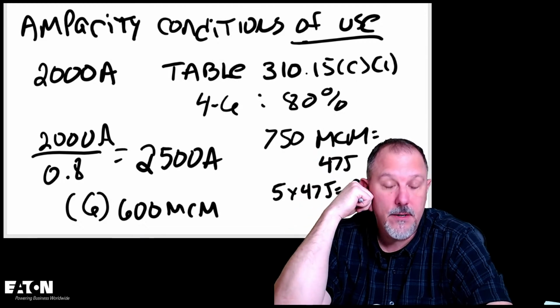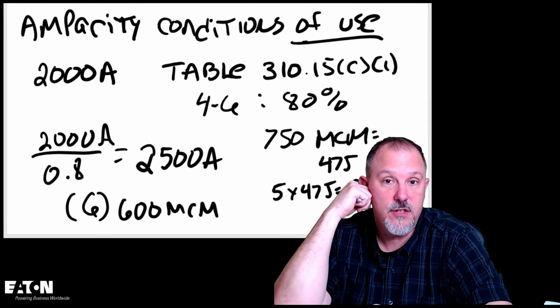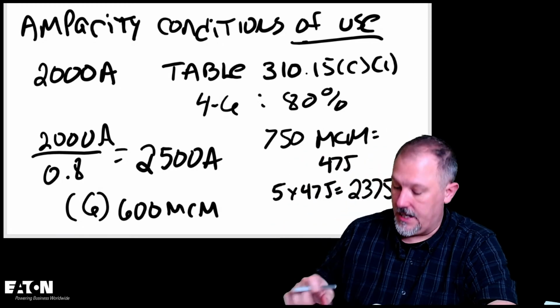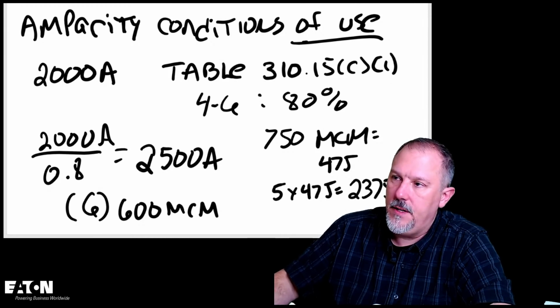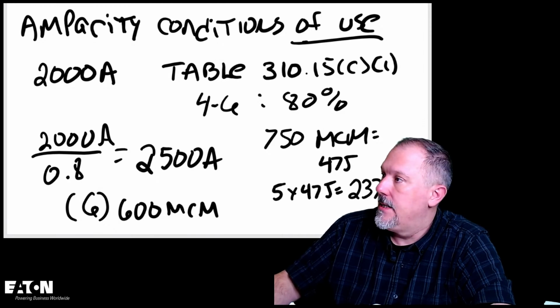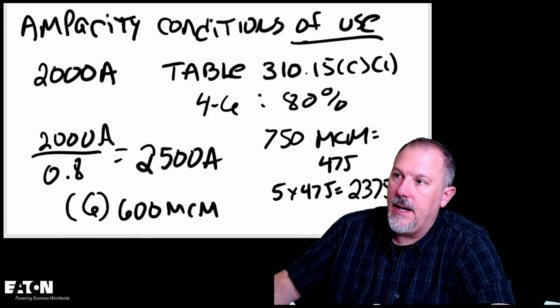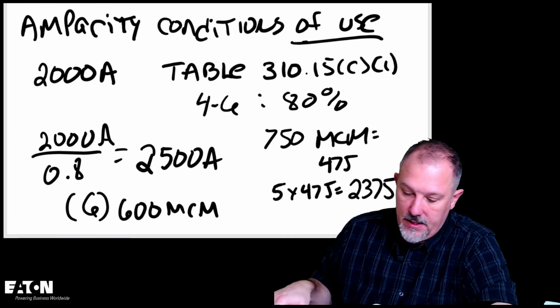Does that make you feel better? It's a little bit better than 750s, Mr. Jackson. So let's change that. Let's just see what happens. If I do this, I'm going to have to go back to my library, and I'm going to go down in size and up in number, same thing. I have to disconnect the library, go back to impedance. I'm going to change my impedance values.